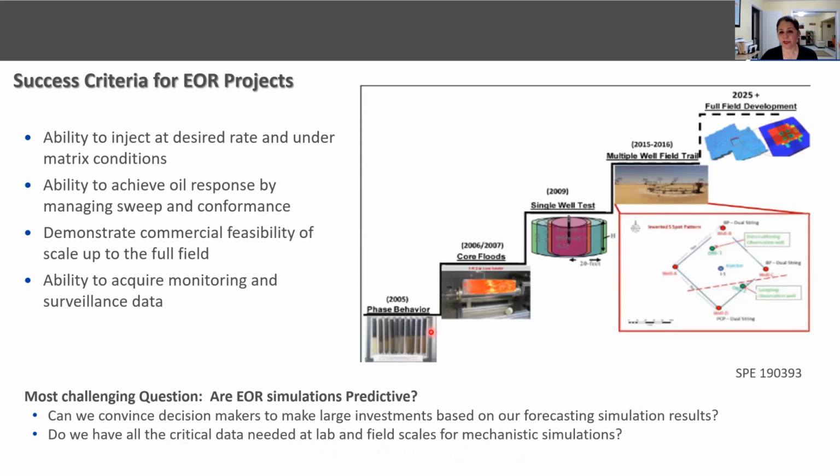And of course, we try to do laboratory experiments. These are for phase behavior with surfactant. Then we do core floods. We may do many core floods. Then we go to the field and we do a single well test to see the response of our EOR strategy. Then we do the pilots with multi-wells, and then eventually we go to full field. So data collection and numerical simulations in every step of the way.